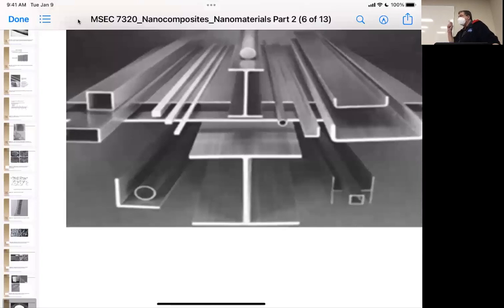Well, that oxide can be fairly dense or not, depending. But now you're putting a very dense crystalline fiber in a matrix right on top of that aluminum to basically bind the native aluminum oxide layer with the fibrous aluminum oxide to create a strong, corrosion resistant and tribological, smoother coating. It's less wearing. Aluminum, if you know anything about aluminum, it galls quite a bit.